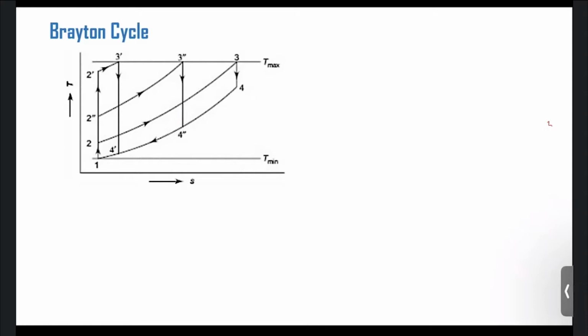Pressure ratio we can vary, but we have an upper limit for temperature that can be borne by the material we are using for the engine, okay. So in the case of turbine engines, they work continuously, on steady flow, so they are always subjected to the high temperature, the highest temperature we can achieve, okay.